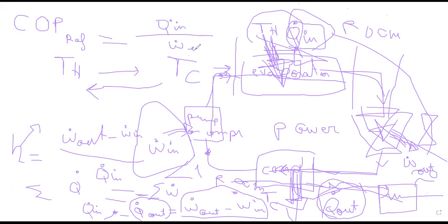So in case of summer, this is how I calculate the COP of my system. While in winter, I want to reject heat to my room. Heat that should be out of my condenser should be given to the room. So my room will be from this side because I will reverse the operation of my HVAC system in a way that heat rejection will be towards my room.